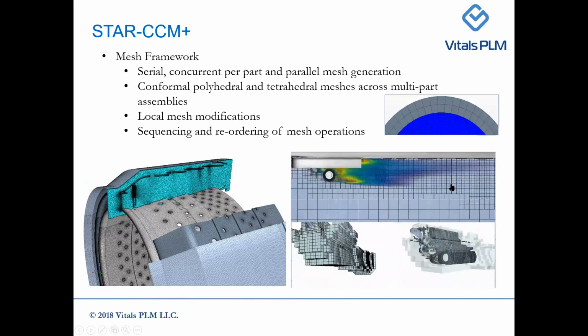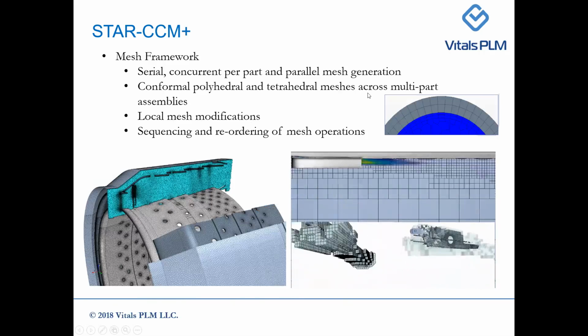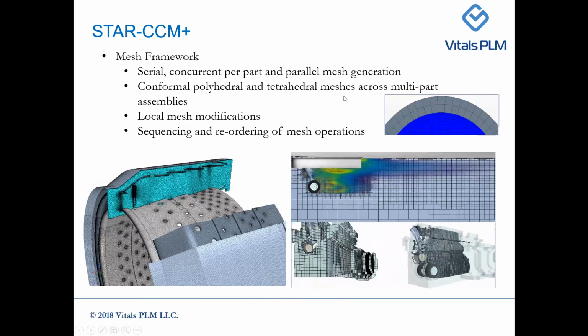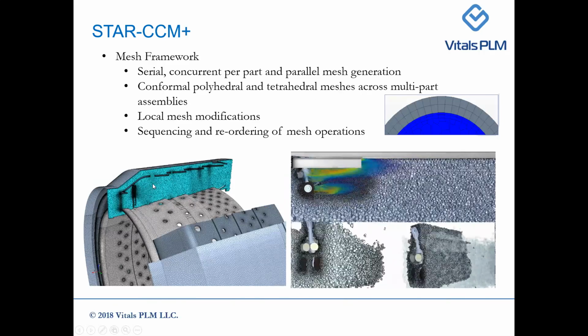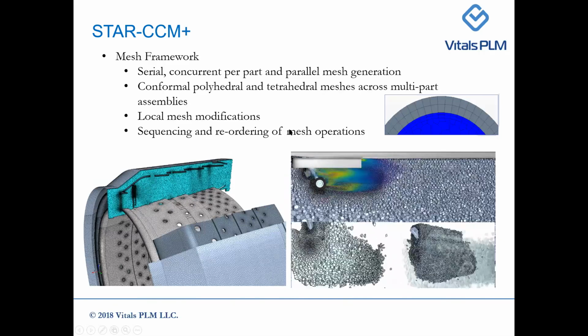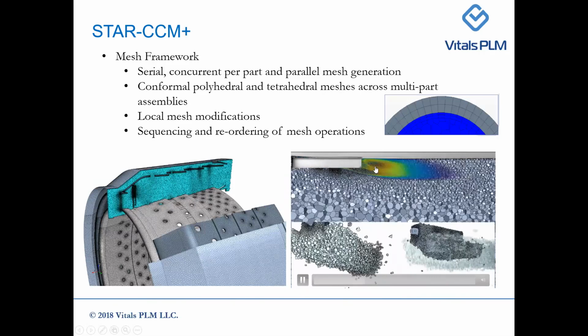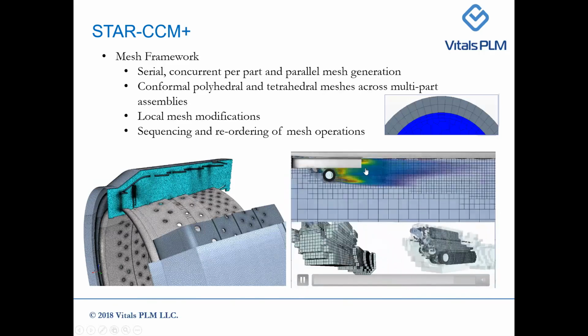Mesh framework. STAR-CCM+ provides a complete set of capabilities for both surface and volume meshing operations. Conformal polyhedral and tetrahedral meshes across multi-part assemblies, local mesh modifications, sequencing and reordering of mesh operations. Here, as you can see, the mesh size varies with the solution.